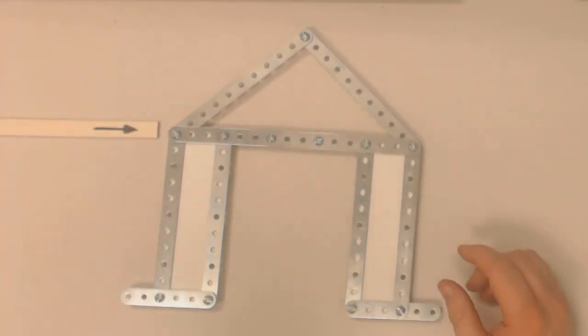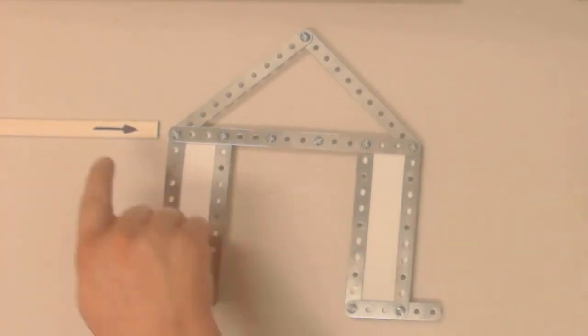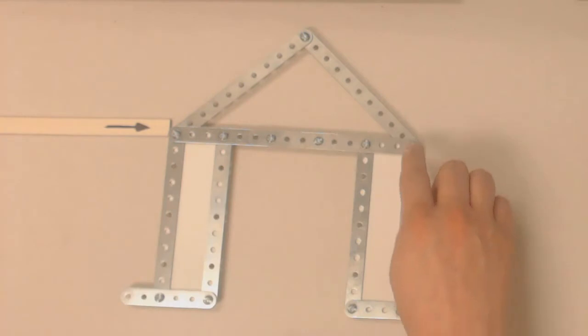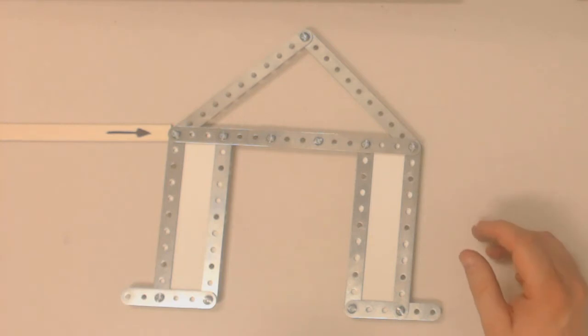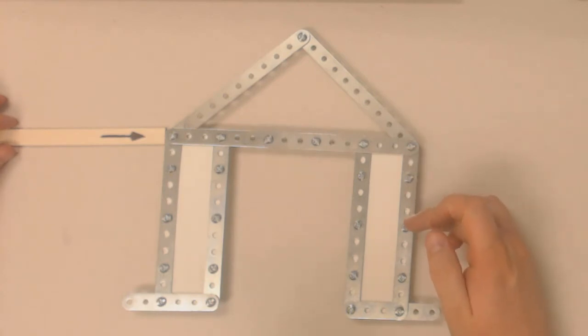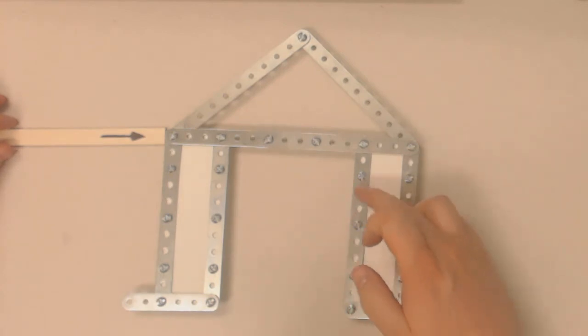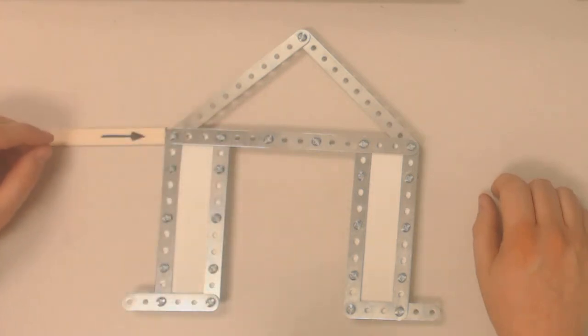And so what shear walls do is they attempt to distribute this load over the entire perimeter of the plywood. And the way they do it is by adding connections to the perimeter of the plywood like this. So now you can see that there are several connections around the perimeter of these shear walls.